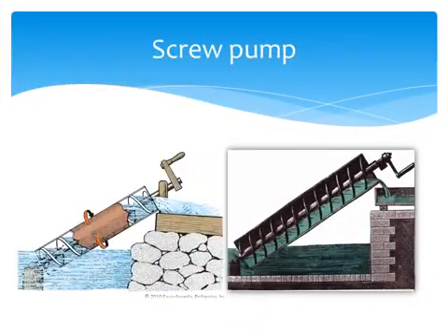A screw pump is a positive displacement pump that uses one or several screws to move fluids or solids along the screw's axis. In its simplest form, the Archimedes screw pump, a single screw rotates in a cylindrical cavity, thereby moving the material along the screw spindle. This ancient construction is still used in many low-tech applications, such as irrigation systems and in agricultural machinery, for transporting grain and other solids.